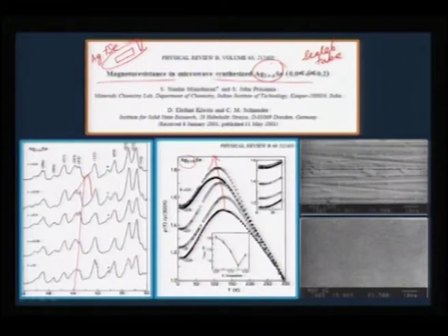This is the SEM image of the silver selenide, and you would see there is no porosity; absolutely more than 99% theoretical density can be achieved simultaneously. So, this is a classic example of using microwave sintering. Not only can you prepare, but simultaneously sinter the compound to the final product.